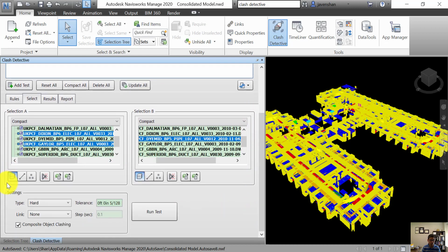And then when you scroll down, you can see some other functions. Typically, I would just use surfaces, and there are other functions. For example, this just says lines, include line geometry in the clash test. You guys can actually look this up, but oftentimes we just use surfaces. And Navisworks can also run clash detection between, for example, a CAD model versus the point cloud. So the other functions, I don't think we really use that very often.